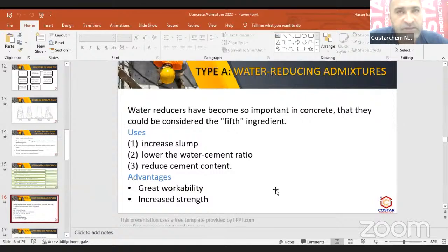If you want to punish somebody, let him try to mix it. It's really very hard on cohesive mix designs. So it looks workable, however, it's not pumpable, and this type of concrete we cannot use.